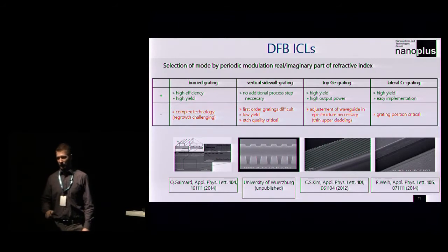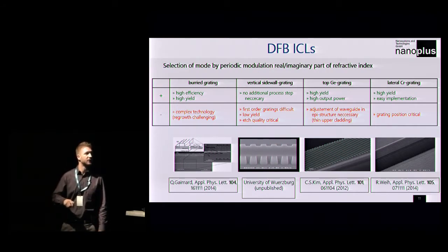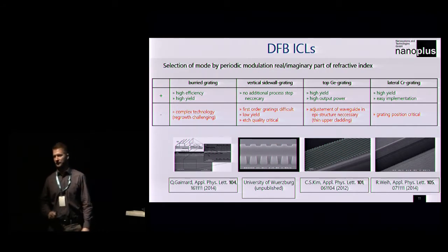So as I said, this is quite a stable system. For example, we have worked with the sidewall gratings here as well, which are quite dependent on the edge quality, so you need really steep sidewalls. So we had way higher yield with these metal gratings.